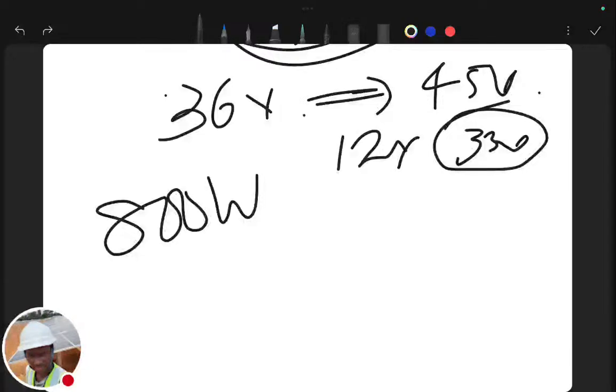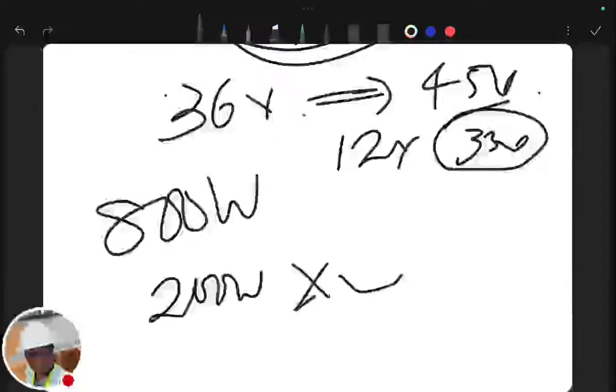You know what, we don't have time. Let me just go ahead and answer it. We need a 12 volt panel, and the max 12 volt panel we can get is 220 watt. God bless you, Mr. Fatai. That's the correct answer. We need a 12 volt. Thank you, Edwin. We need a 12 volt panel, and the max 12 volt panel is probably 200 watts. So multiply that by 4, we have 800 watts.